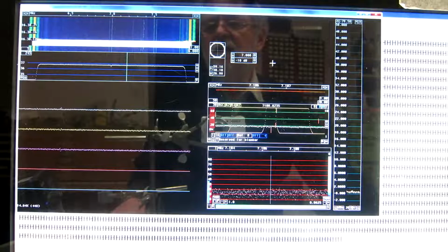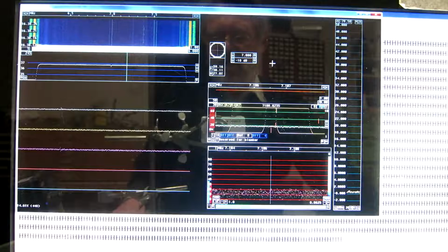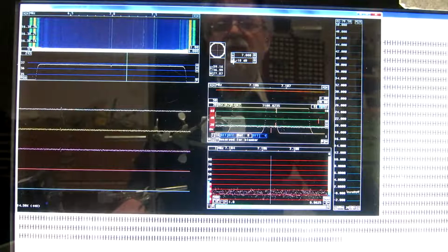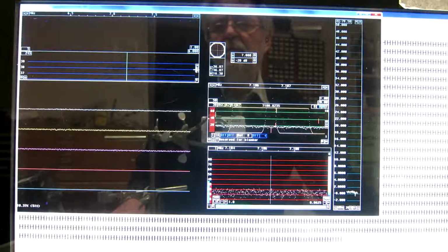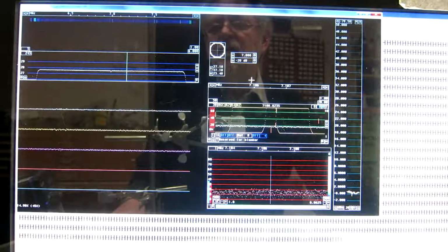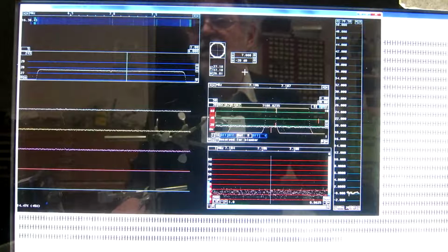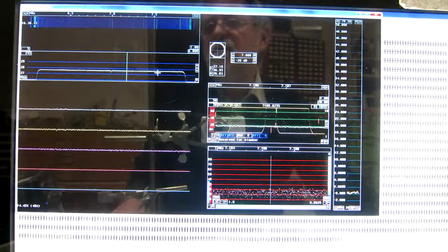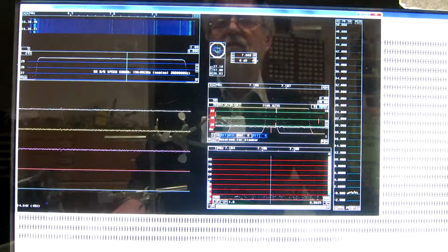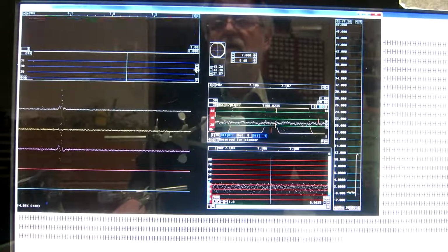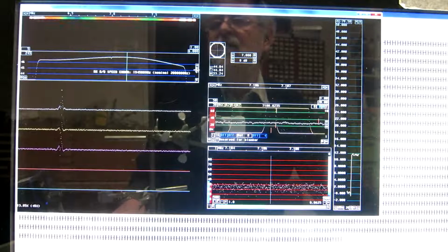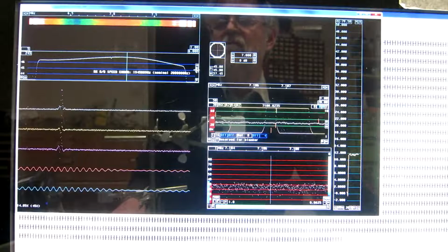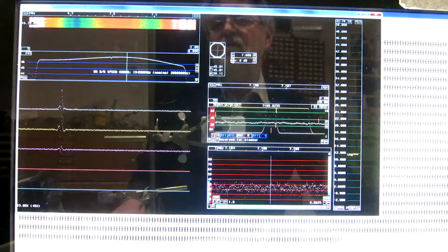But the calibration is now reasonable. I check by going down 10 dB more. Sorry. And you can see another 10 dB attenuation does not change the frequency response much, but if I go up to 0, there is a problem. Strong mismatch changes the frequency response.